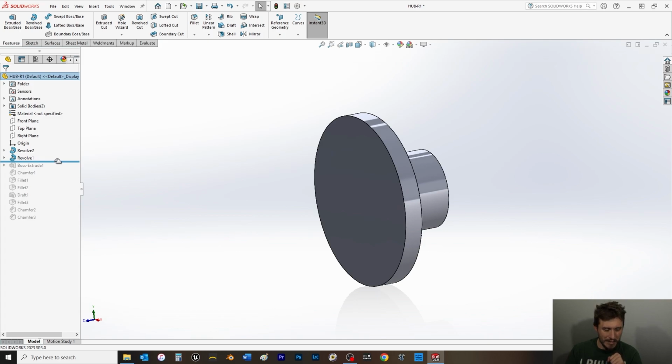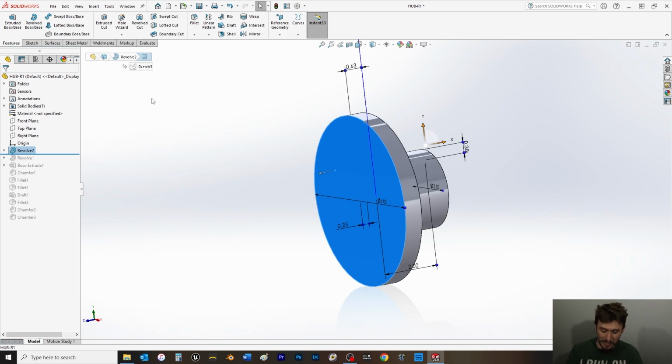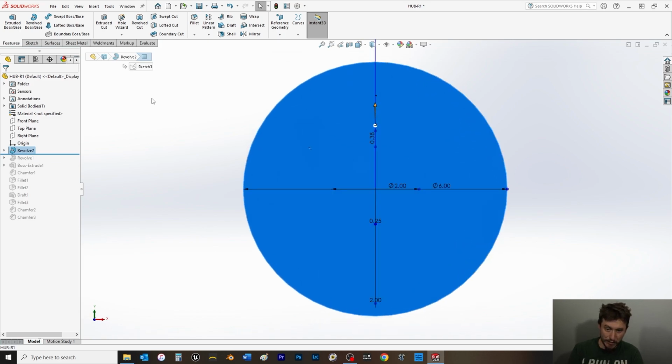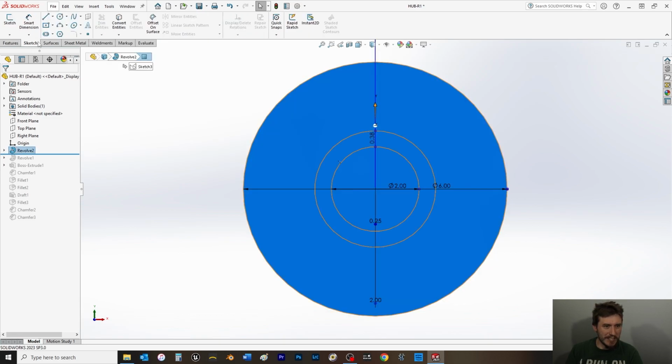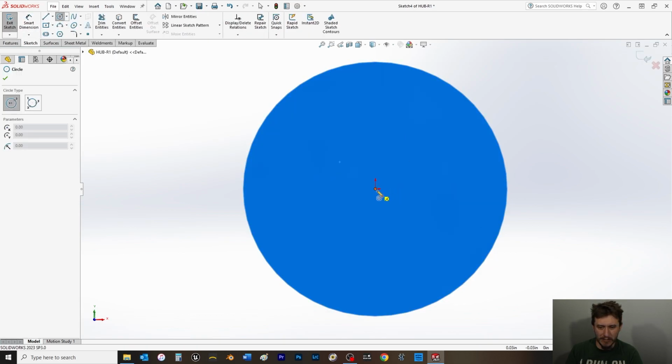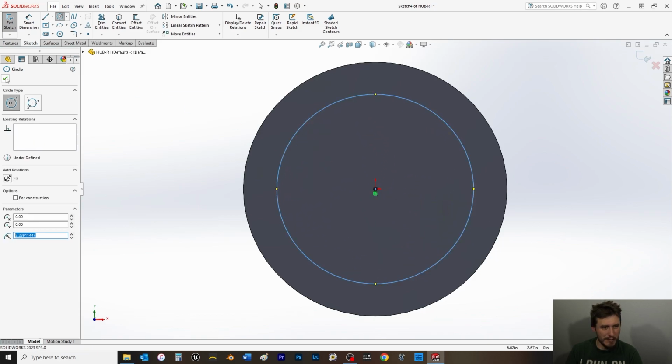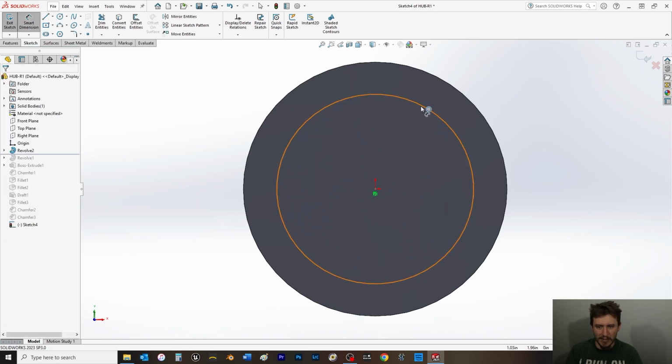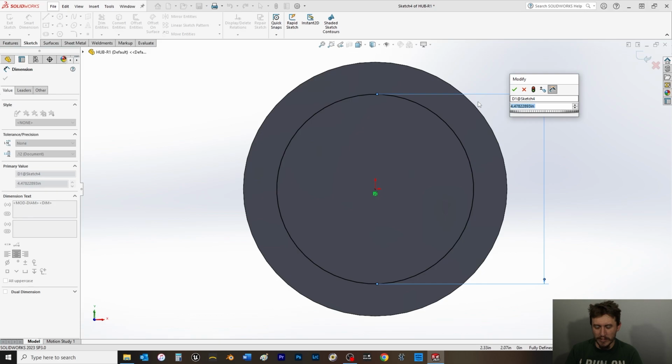But now, I'm going to throw it back. We're going to select this front circular face here, Control-8 to bring it normal to. Go to our sketch tab, start out with a circle, crack it open to about here. My dimension that I pulled from the wheel is going to be 3.625.